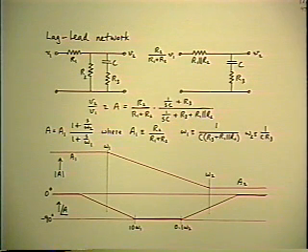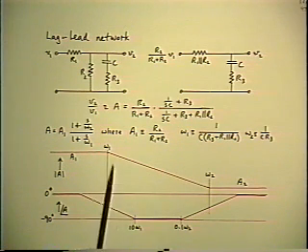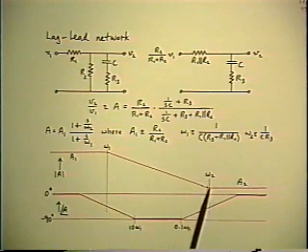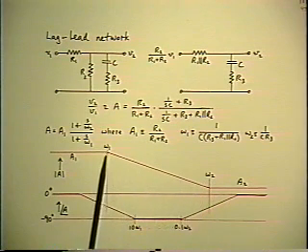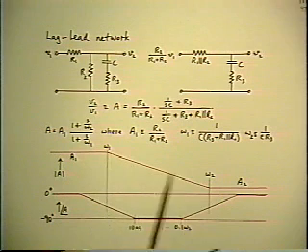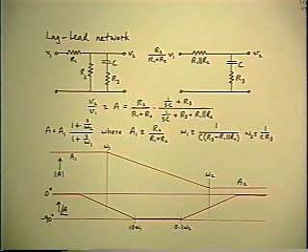Now, that's actually pretty obvious, because this slope, after all, is 1 for 1. It's simply a reciprocal function of frequency. That was its origin, which we already did. So it follows directly from that even, that the ratio of the two flat gains is the same as the ratio of the corner frequencies. But it's a very simple thing and very useful.